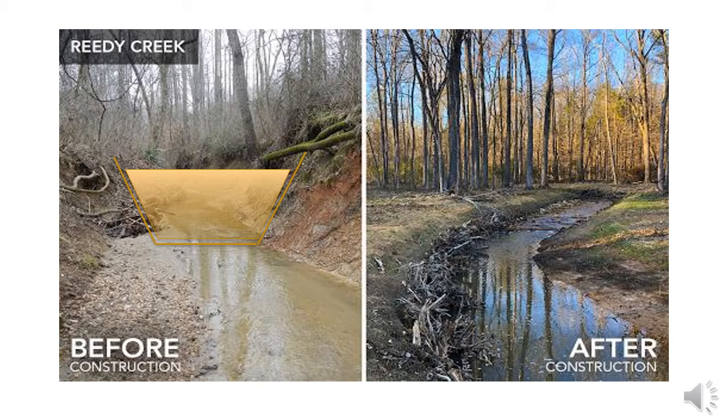It more or less basically says that the landscape surrounding it did not allow this stream to move its course or change course during periods of high peak flow. And instead, what happens is that it continues to erode right through the gravel base of the streambed, right into the softer soils surrounding it. The stream gets wider, the stream gets deeper. This is a common occurrence over time. As you project forward into what's going on the right, the whole point of restoration is to solve that problem. How do you address the V channel, and how do you do it in a way that you can actually manage this issue in the long term?